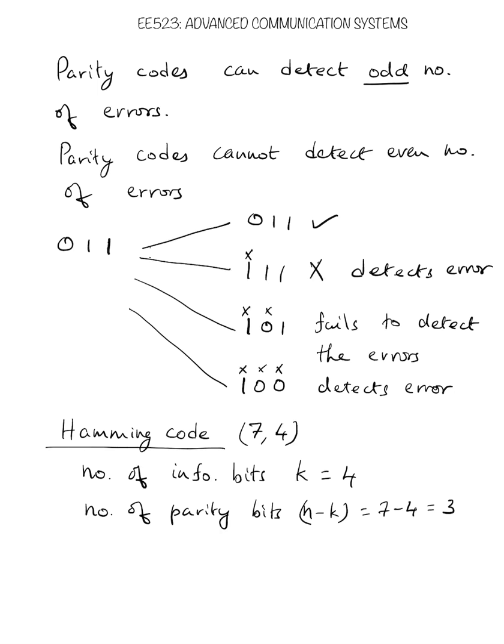So we are going to take 4 information bits at a time, and for them we are going to add 3 bits according to some rule, and the total block of 7 bits will be transmitted. For every 4 bits we are going to add 3 parity or protection bits. So the code word length, or block length, n is equal to 7, right? So what is the code rate in this case?